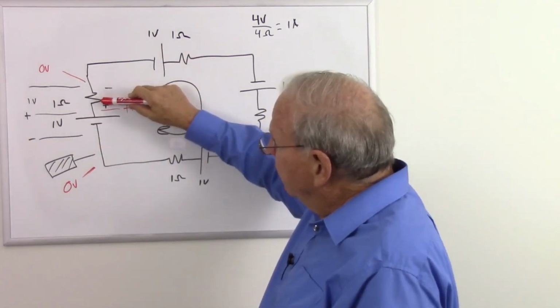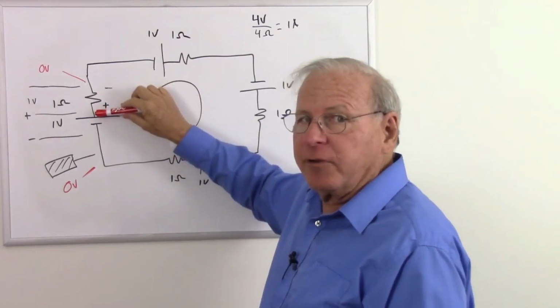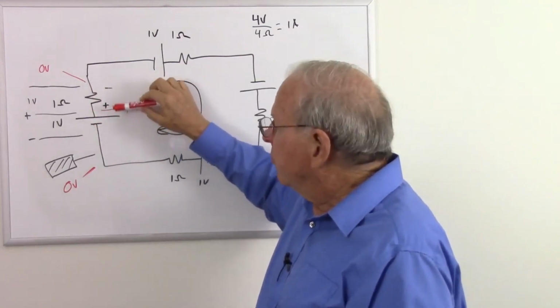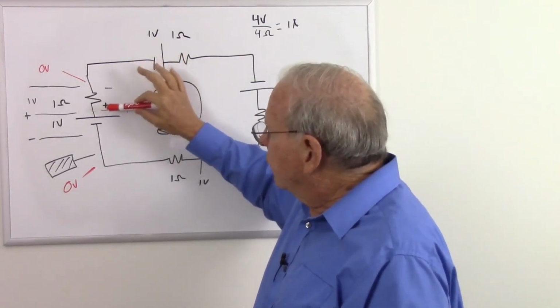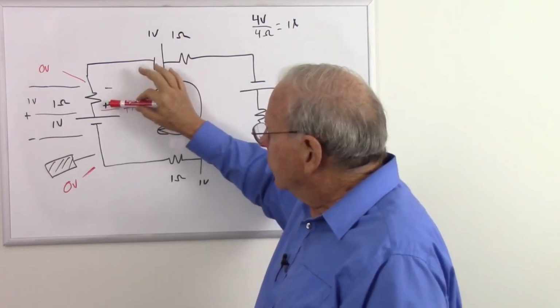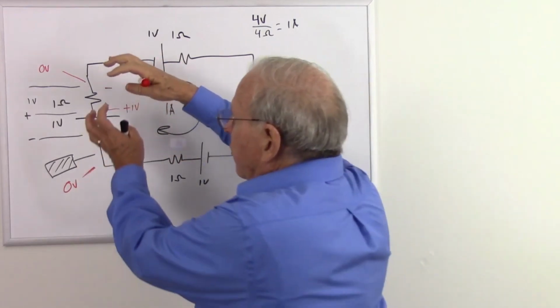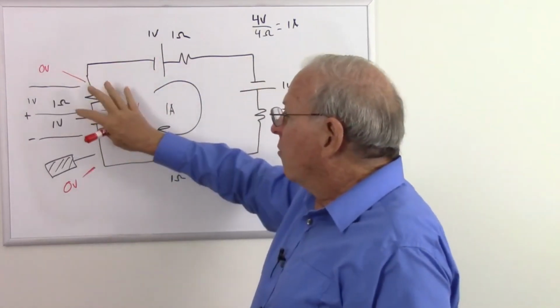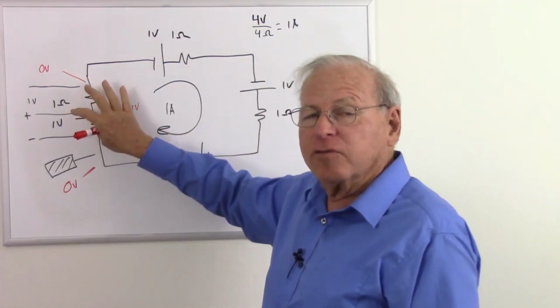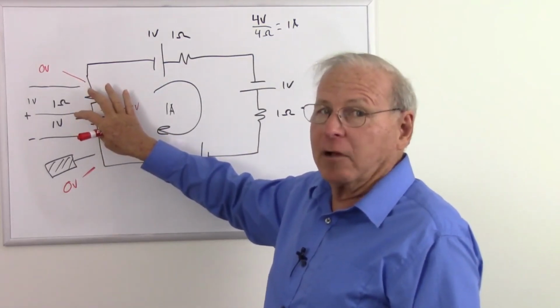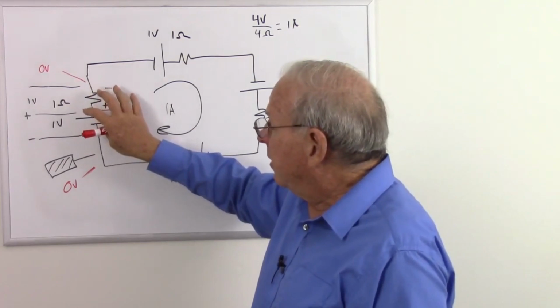So that's why no matter where I put my meter around that loop, remember we can't separate these. We model them in series, but I cannot put a voltmeter between my voltage source and the resistance. I can only do it in this thought experiment to show that I gain a volt and lose a volt, but the truth is they're one entity. So across there, I both gain and lose a volt at the same time. Kind of boggles the mind, but that's obviously what's happening.